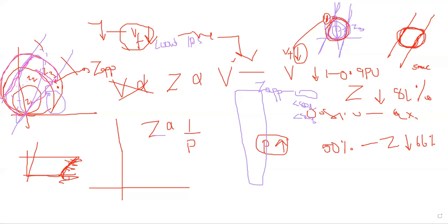That cannot be. In 220 kV, the voltage would be like plus or minus 10% or plus or minus 5% only. Right? So if I am seeing that the voltage is falling much beyond this, then I will assume that, oh, this is a fault, not based on the load encroachment or power swing. So what I will do, I will disable this feature automatically. So it will see the whole characteristic and it will identify what zone it is coming under.